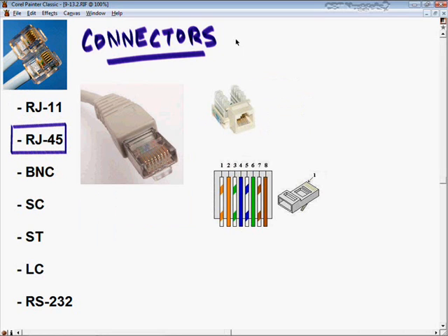These RJ45 jacks have actually replaced the older connector types like BNC connectors that we're going to talk about next. As we talked about, from a wiring standpoint, RJ45 jacks are frequently terminated using the T568A, or nowadays the T568B, pin pair assignments in category 5E and category 6 cable.